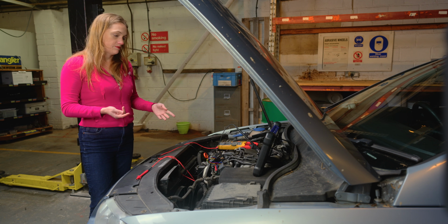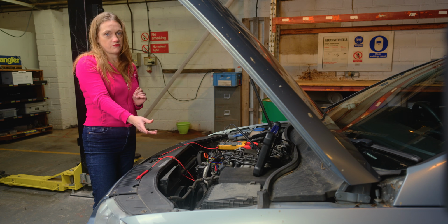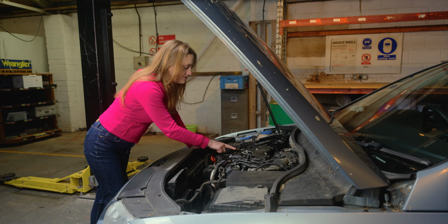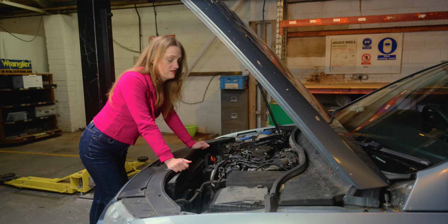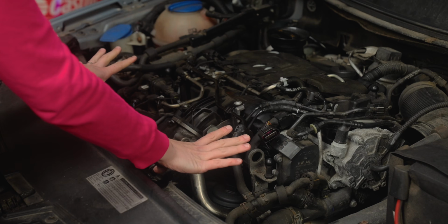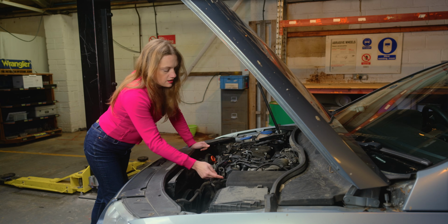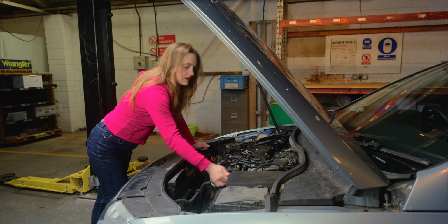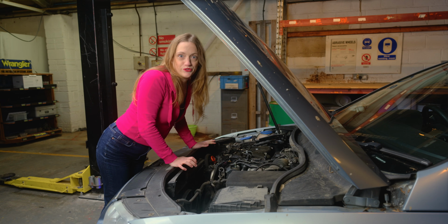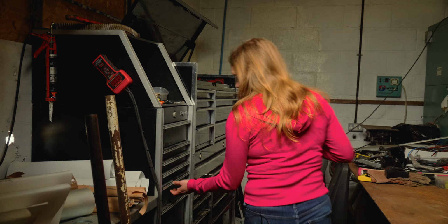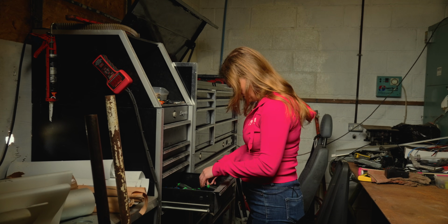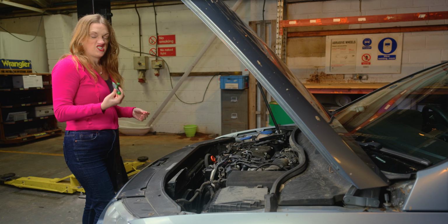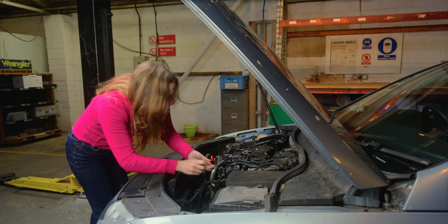There's no way of accessing the flaps, so I'm just going to pull the cover off the motor and see whether I can manually move them. The flaps are in here, which is pretty impossible to get to. You've got to take off all of this. So no. I'm going to take off this cover and I'm going to see if I can access the gears and move it manually. Let's get some more tools. 25. They're just a Torx 20 and I've got my T-bar.